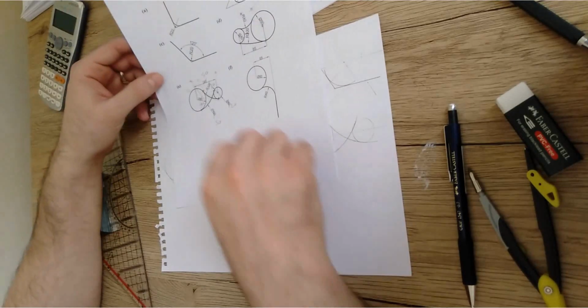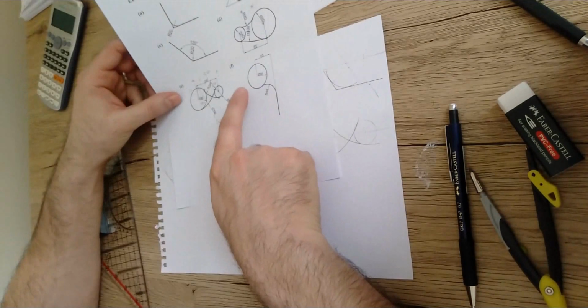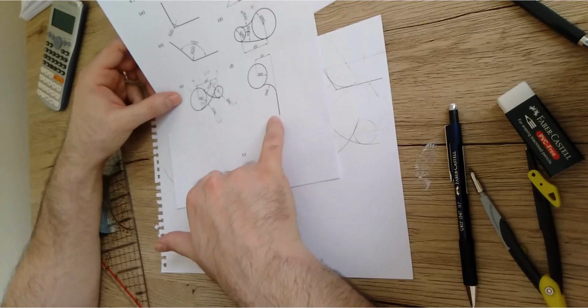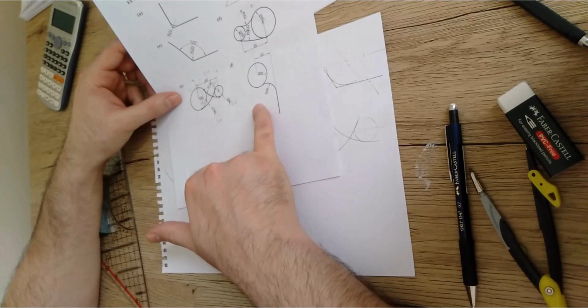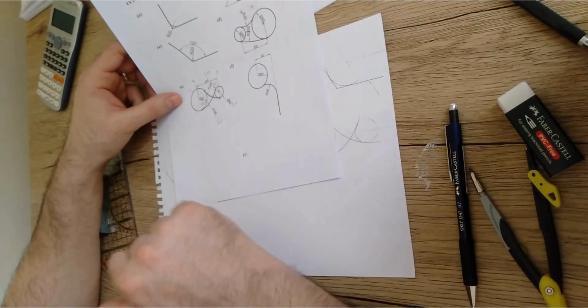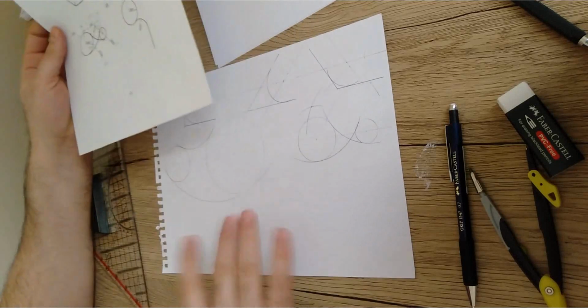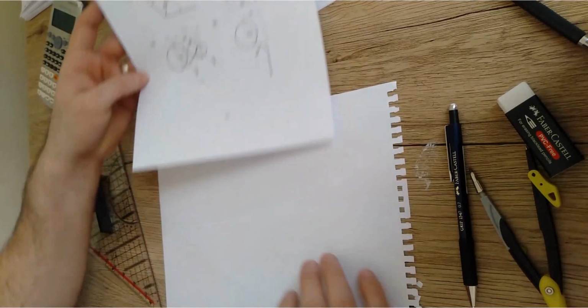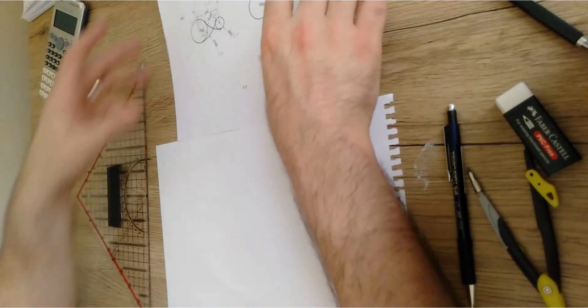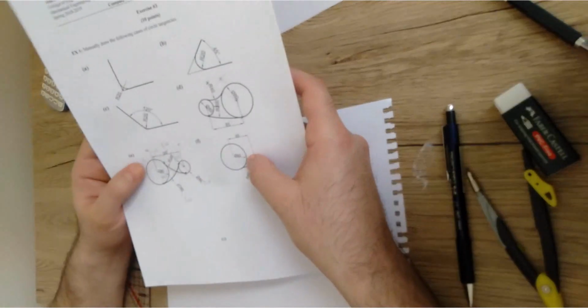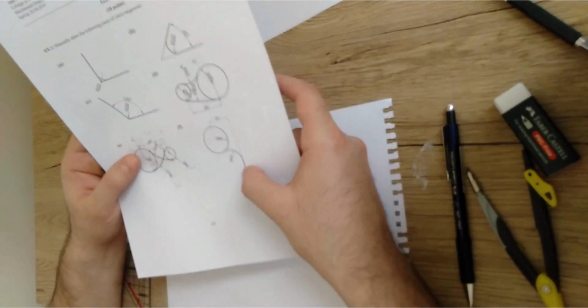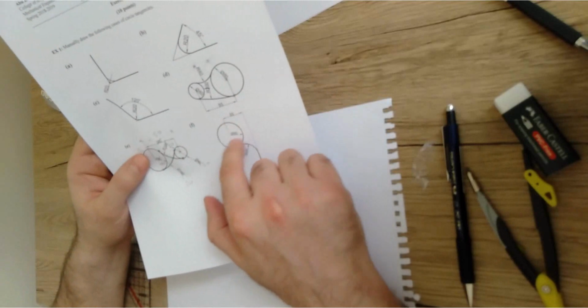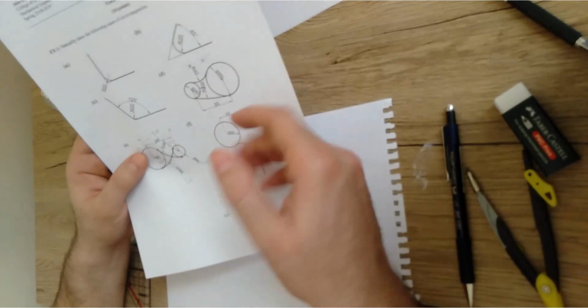Now I'm gonna move to the last example here for the case that we do have a circle and line, and the curve is tangent to both a line and a circle. For this example, I'm gonna use the back because I don't have any space here. In the beginning, I'm just gonna draw the line and the circle, and the diameter of the circle is already given by 80. It means that it has a radius of 40, and the line should be at a distance of 65 from the center point in the horizontal dimension.